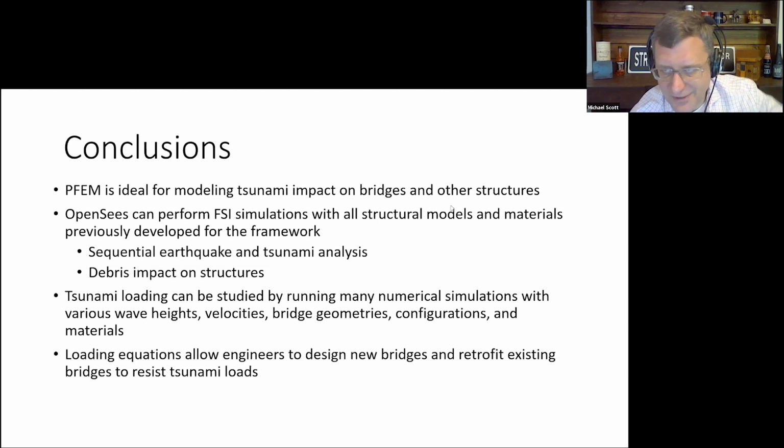Yeah, so the approach we used was to get the maximum credible flow height and speed, and then I kind of skipped over this detail in the presentation, so it's a good question. From the PWI experiments, we looked at the distribution of horizontal velocity and vertical velocity as the bore was approaching the bridge. And then, from that, we mapped out those simplified profiles of horizontal and vertical velocity. So those were based on tracking the flow during those experiments, or in the numerical simulation of the experiments, and idealizing that as the tsunami flow condition for all the numerical experiments we did on the bridges later in the project. So really just tracking the fluid flow and then idealizing that.